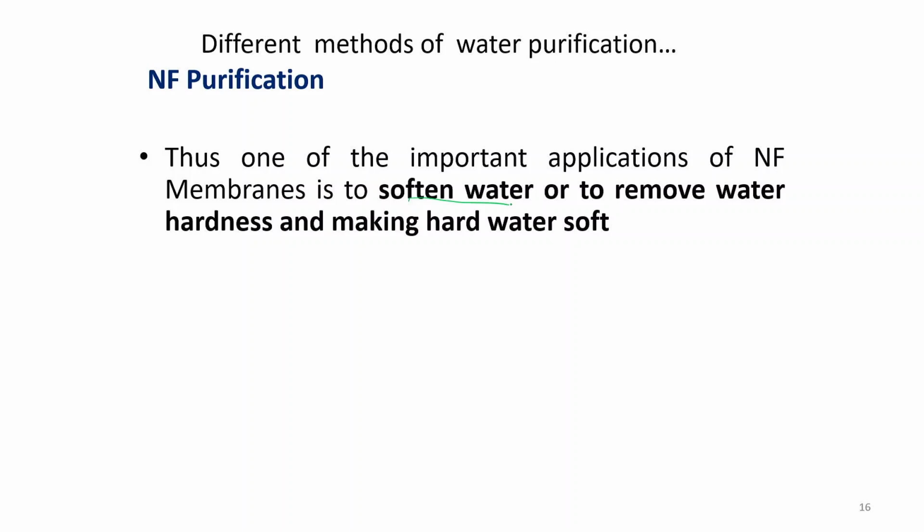If you want to make the water soft, we can always use RO, but it needs higher pressure. That is why, for softening the water, we use the nanofilter, to remove any hardness from the water and to make the water softer.